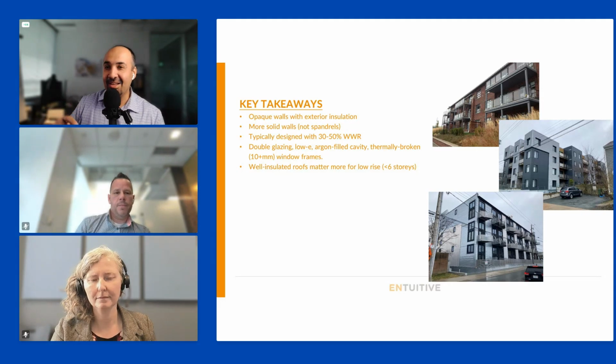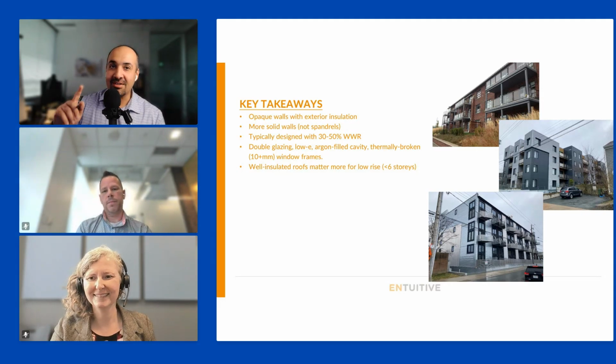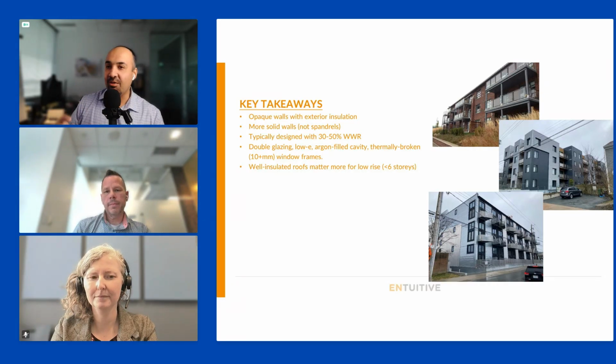I get the privilege of actually asking my own question here. Balconies. We've had a very hard time with balconies, trying to reasonably solve the thermal bridging. Are we alone, or is that a general situation that, if you want to go for these high performing buildings, there's a very good chance you're going to have to get rid of your balconies, or at least have complications with it? I think the easiest strategy would be to make them smaller and put in thermal breaks.